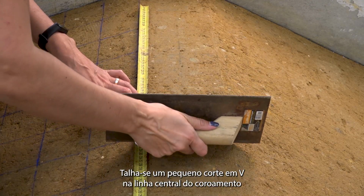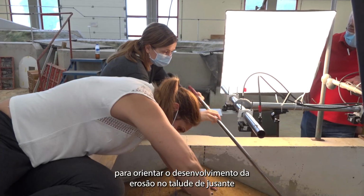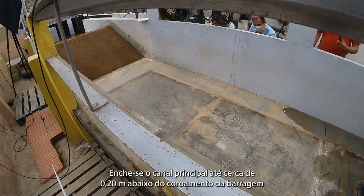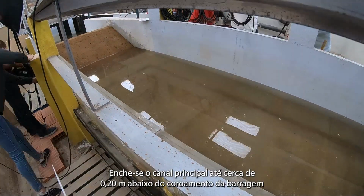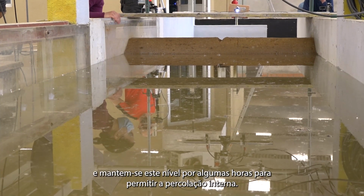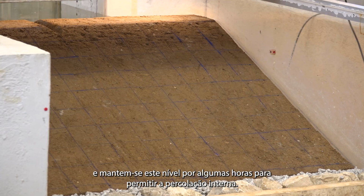A small V-notch is carved in the centre line of the crest to guide the development of the erosion incision in the downstream slope. The main channel is filled up to a level of about 0.20 metres below the dam crest. This level is maintained for some hours, allowing for internal percolation.